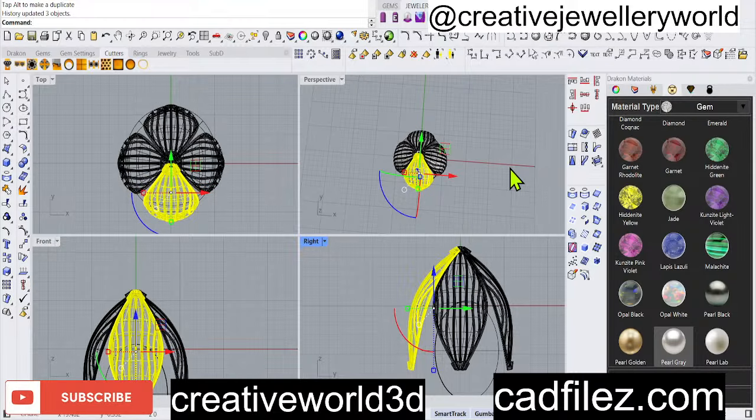If you want a set number of items in a required angle, then you can change the option. Instead of 360, you can change it to 270 or 250 or whatever your required angle, whatever the limited space you want your objects to array. I want 360, so I didn't change anything there.